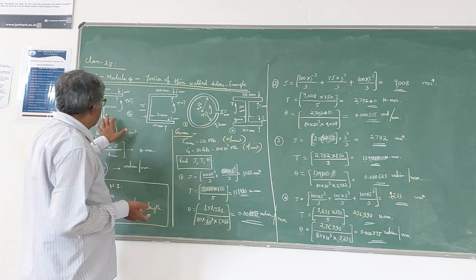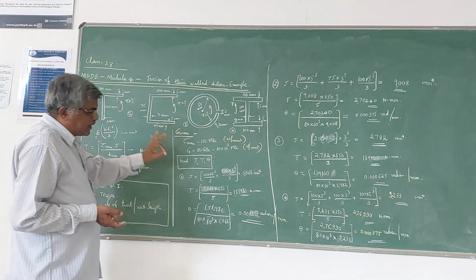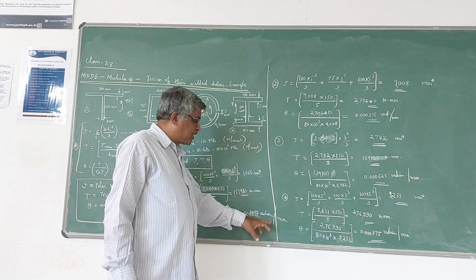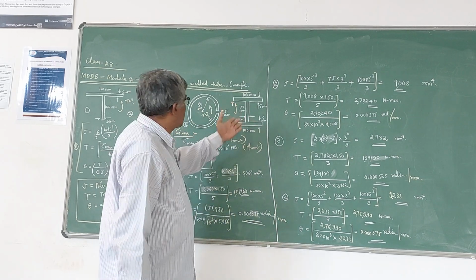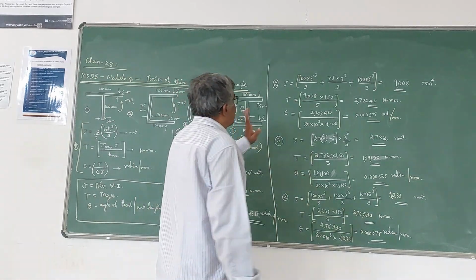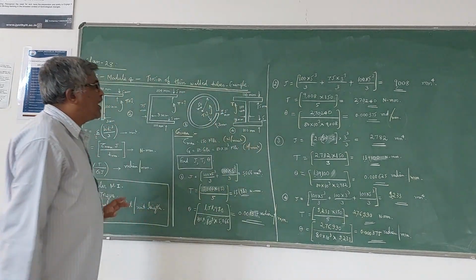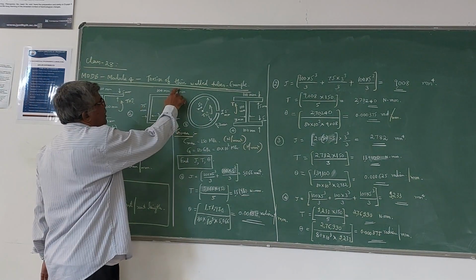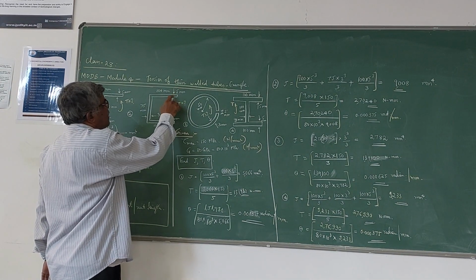In the first case, this type of tube can have an angle of twist of 0.30375 radian per mm. Next, coming to the second type, that is a channel section or C section. Same formula for J, Σbt³/3. Here there are 3 rectangular sections, 100 into 5 cube, thickness is 5 here, divided by 3.